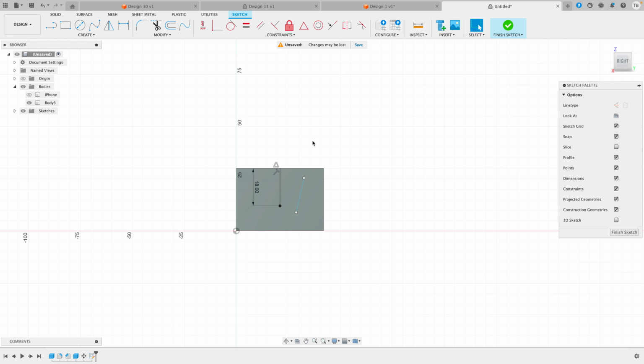So in Fusion 360, the proper way to design something is to design things fully constrained. That way, if we want to go back in our timeline and change the dimension of something, you could always just go back to that dimension and change it. Now this triangle here, that's our midpoint constraint. You'll notice here, I selected it and you can see it's actually telling us what it is. It's the midpoint constraint. Basically means that this line here has to be on this midpoint.